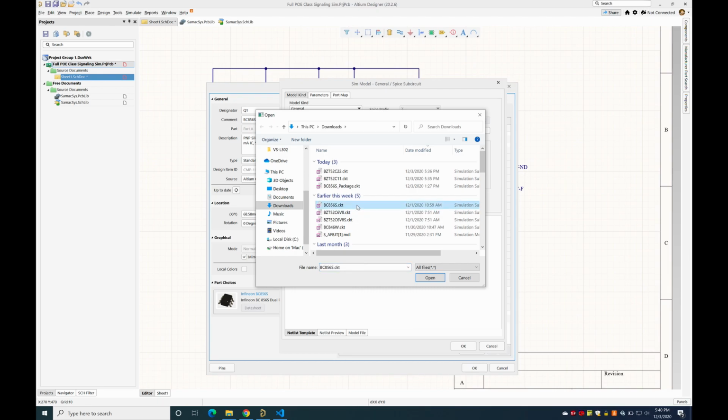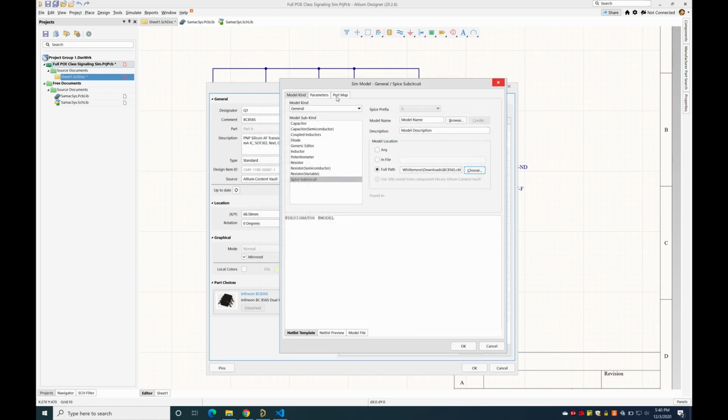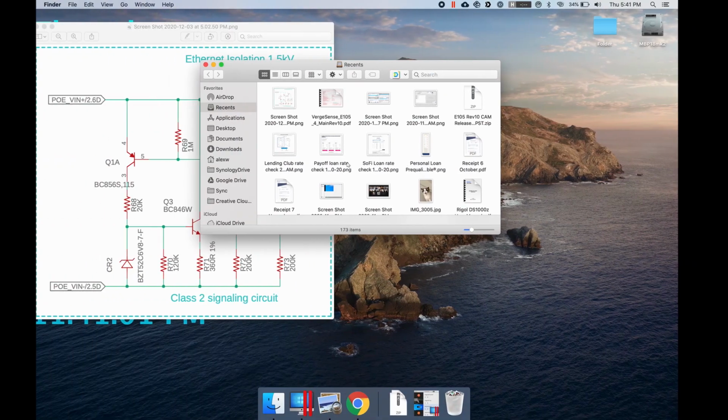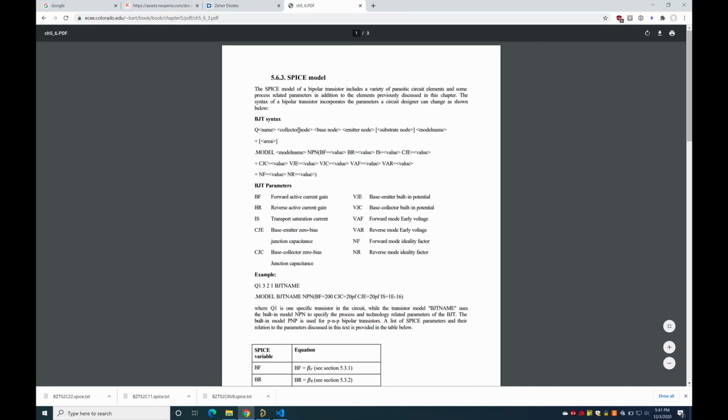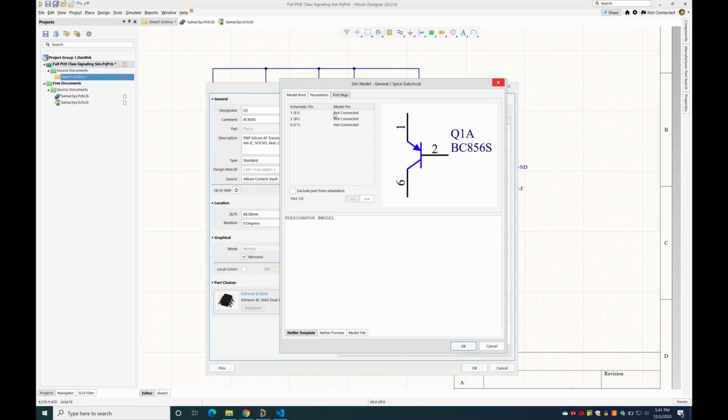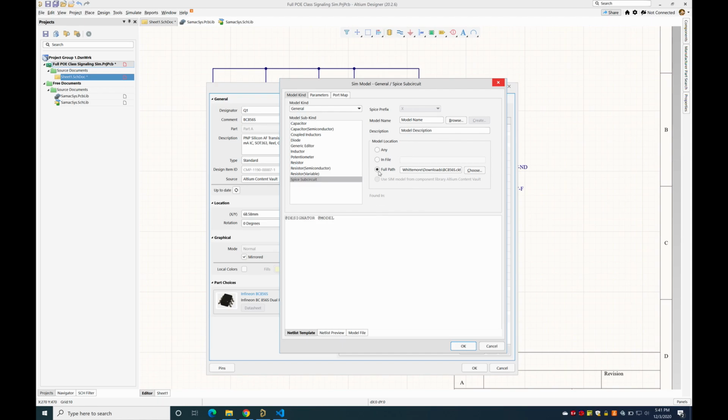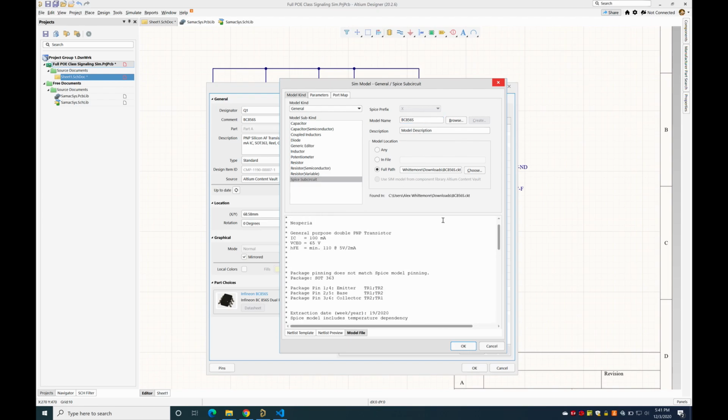What's a little bit confusing about this is not all packages behave the same way. For instance, Eagle assumes that a SPICE model has to have the same number of pins as the package component does. And in a lot of cases, this makes the most sense because, like, an op amp has power pins that are shared between all of the parts. So how would you map an insufficient pin count symbol to a model that has more pins? I'm not quite sure, I haven't sorted that out, but in any event, this is how you do it in this particular case. Just assume that they're separate components and everything will be happy.